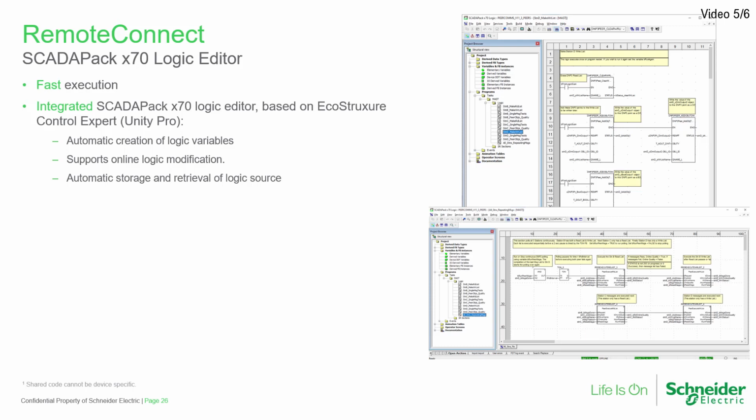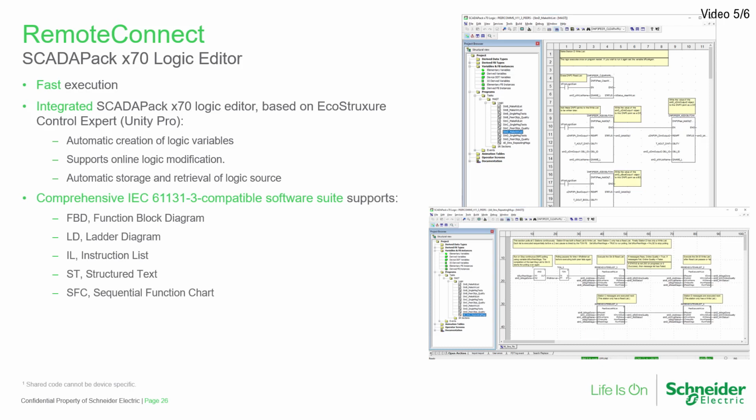The Logic Editor also provides a comprehensive IEC 61131-3 compatible software suite that supports all 5 IEC 61131-3 logic languages: FBD function block diagram, LD ladder diagram, IL instruction list, ST structured text, and SFC sequential function chart.